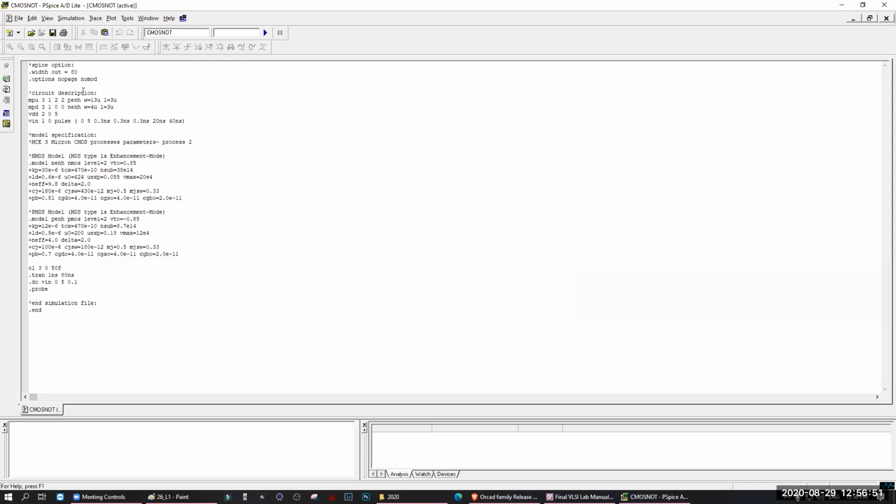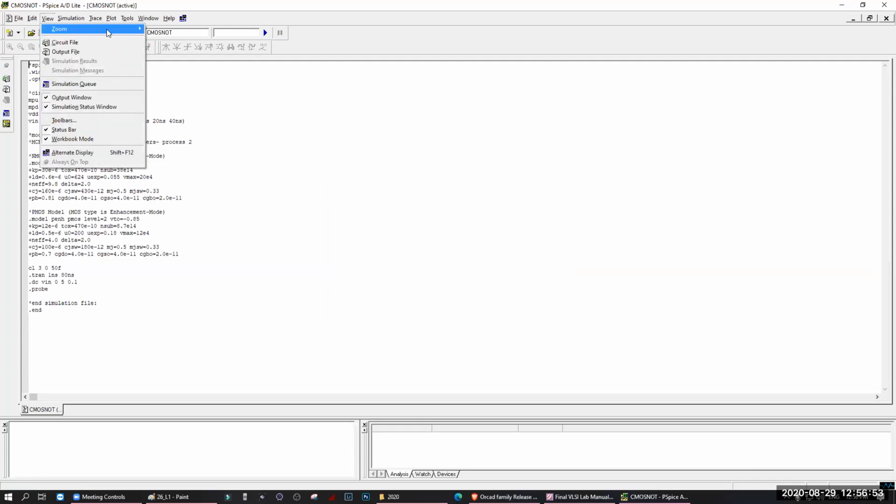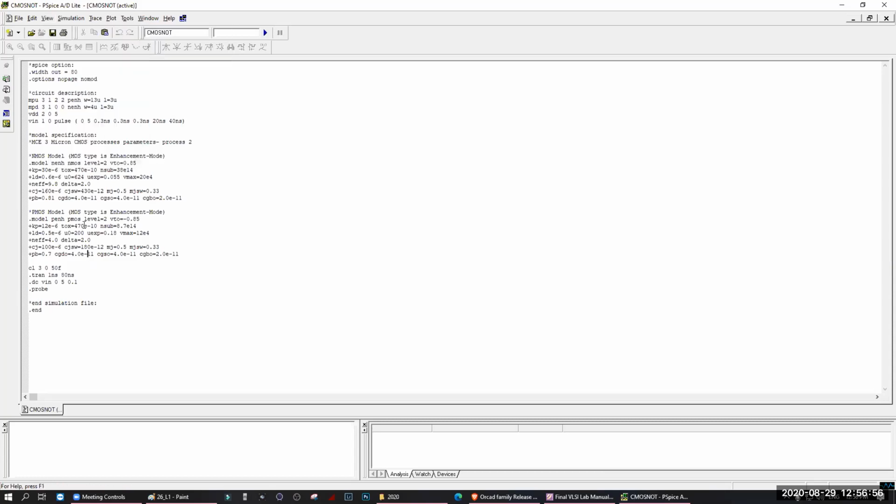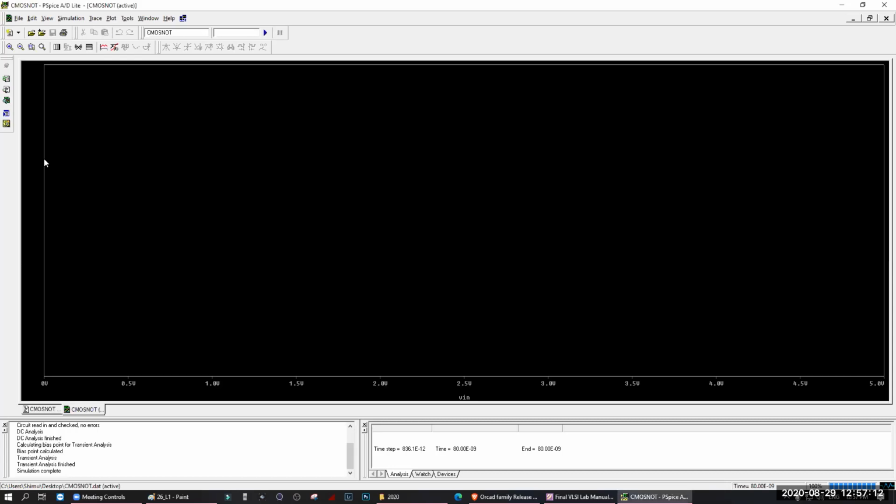I'm going to make it bigger. View. How to make it bigger? I do not know how. Okay, no problem. Now I'm going to run the simulation. Run. If there is any error, here you will see it. Now I want to see the DC analysis first. DC. Here, nothing is shown, right? Because we have to tell it what we want to see.